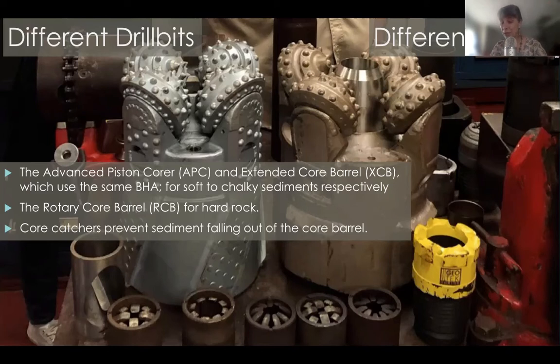Our chalk started turning to limestone, and then eventually we entered mudstone, and we had to use drilling bits. And so these drilling bits go round and round and round, and they cut a circle of rock in the middle, and that's what ends up in your core.